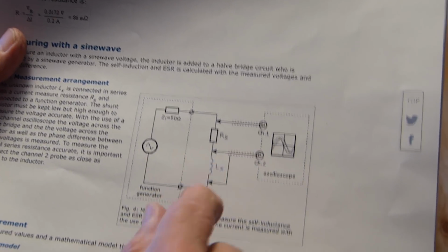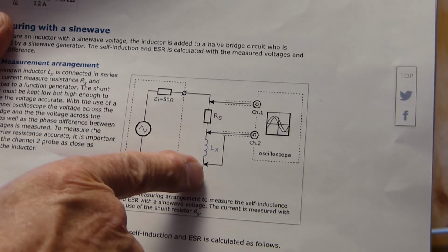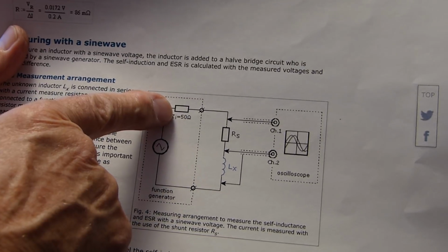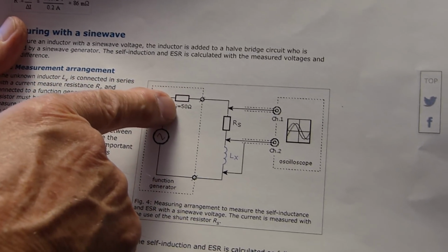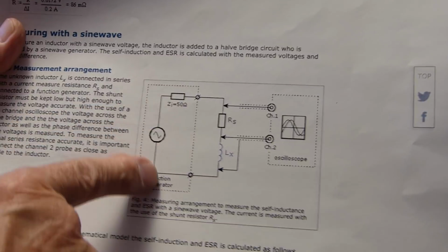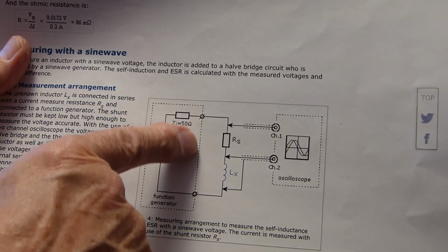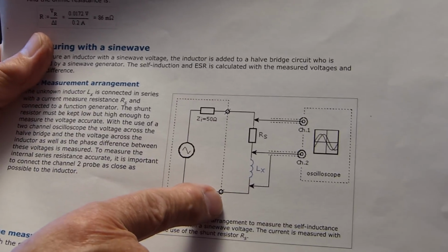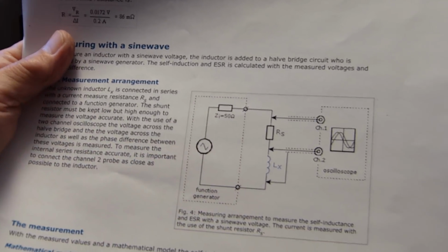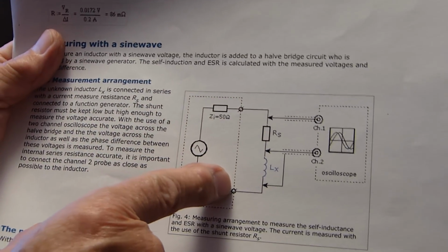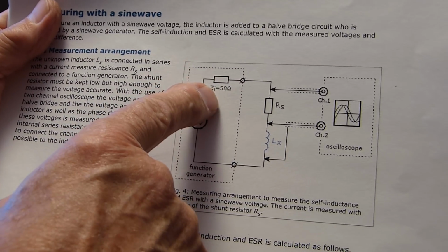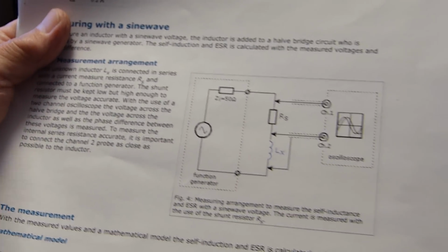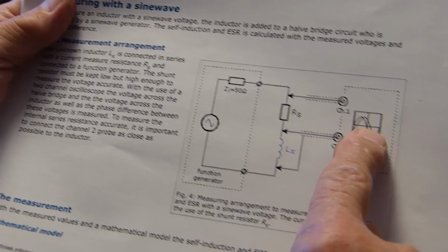What we're going to do is measure the voltage across the inductor, and measure the voltage across the resistor. The internal resistance of this particular generator is 50 ohms. Well, since our generator is a 600 ohm, what I've done is I've put a 10 ohm resistor across it right here. It's not shown in here, but it is in my LT Spice model. You put a resistor across here to swamp this so that this does not become a significant part of the equation. So we put our scope here, and what we do is we measure the phase difference.